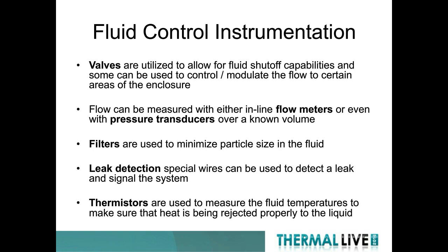We see filters are used to minimize particle sizes in the fluid. Leak detection has special wires that can be used to detect a leak and signal the system. We see leak detection used with valves for shutoff capability. And thermistors are used to measure the fluid temperature to make sure that the heat's being rejected properly to the liquid.